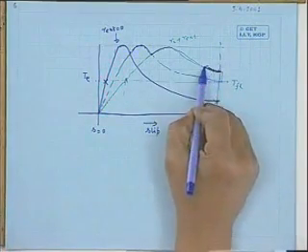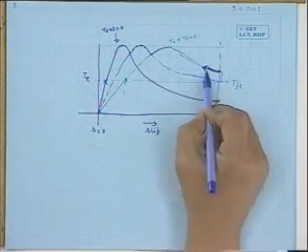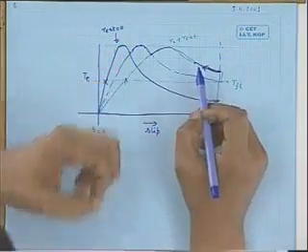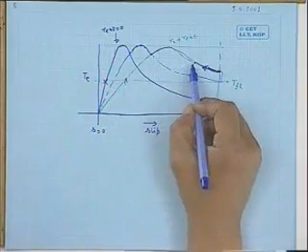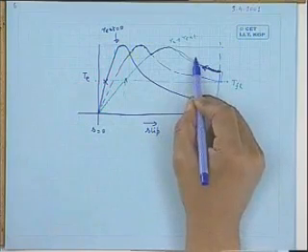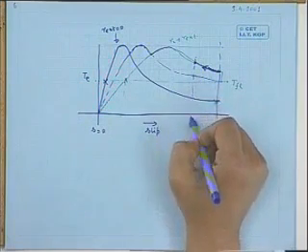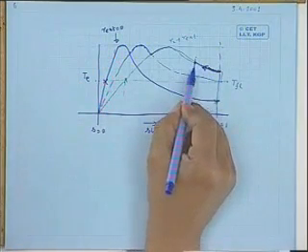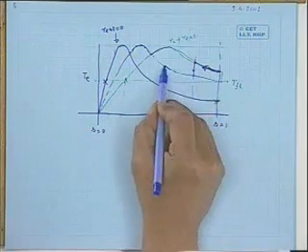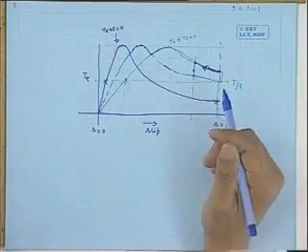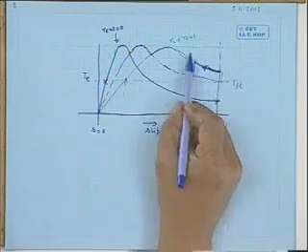Well, what I am trying to tell is, suppose the machine is moving like this, it is the curve, okay? Suppose at this point some R external is changed, reduced. So at that point of time, what will be the torque slip characteristics? The machine will refer to this. So the point of operation will come here, then it will move the way you change it. Is that clear?